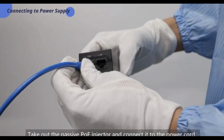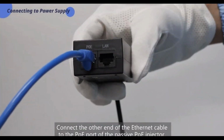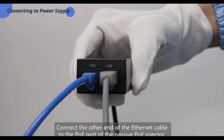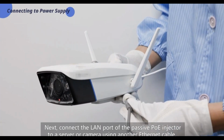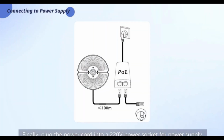Take out the passive PoE injector and connect it to the power cord. Connect the other end of the Ethernet cable to the PoE port of the passive PoE injector. Next, connect the LAN port of the passive PoE injector to a server or camera using another Ethernet cable. Finally, plug the power cord into a 220V power socket for power supply.